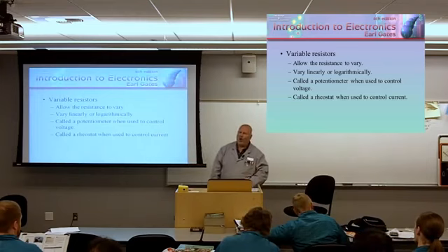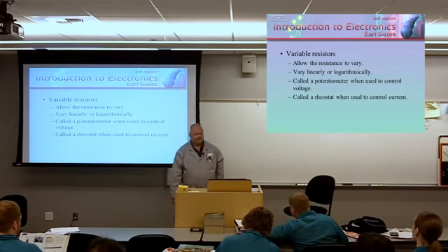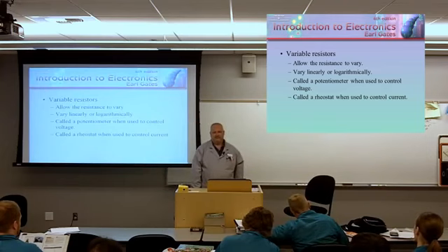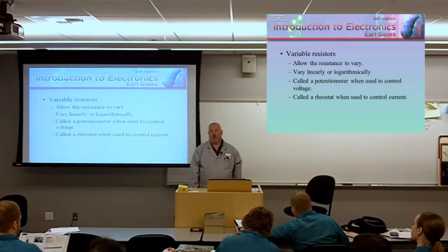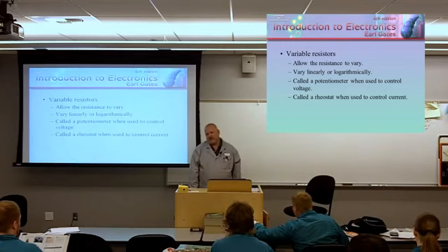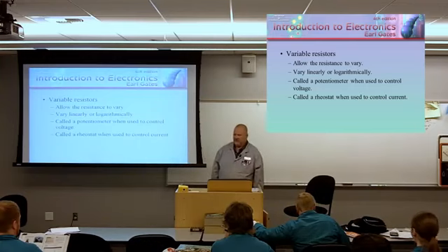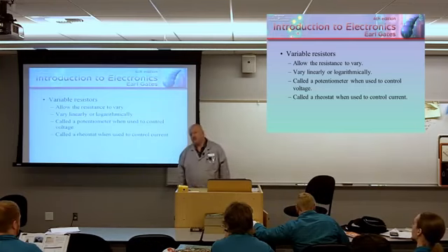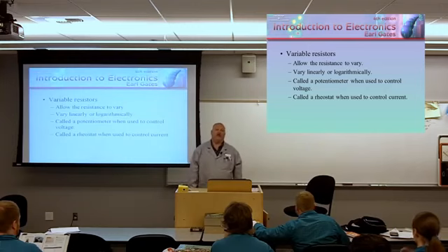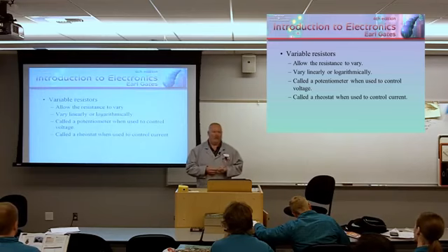Logarithmic is used for audio applications because audio is not linear. Audio, some of you may be aware, is measured in decibels, and that's on a logarithmic scale. So if you want to control something that is nonlinear, you need to use a control that's nonlinear, and audio is that example. That's why we have this logarithmic control.